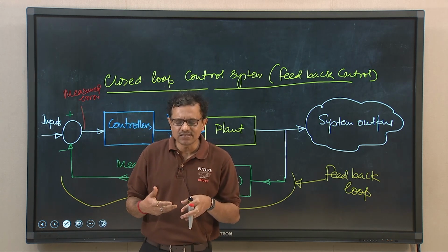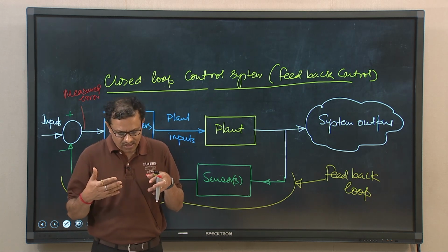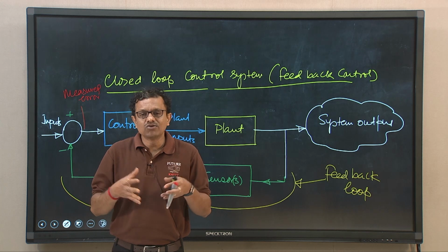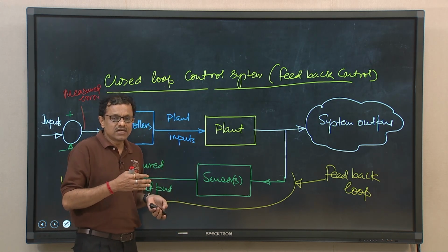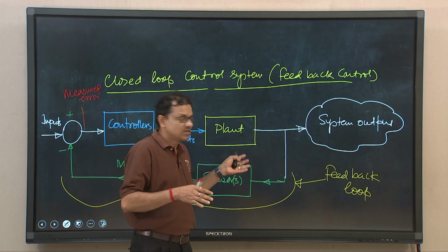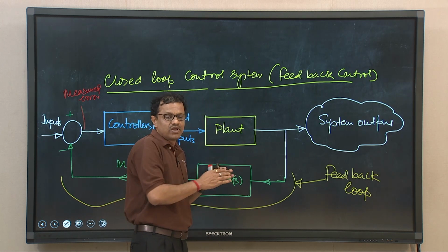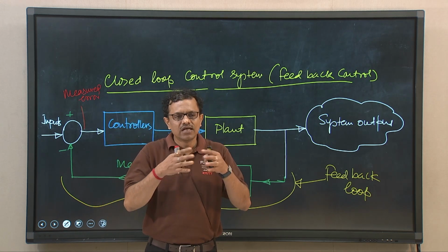In most engines, closed loop controllers are complemented with feed forward aspects, certainly to improve response time. Let me tell you one thing: though the electronic control unit is capable of doing all these things, the feedback loop allows even finer control of the entire system.